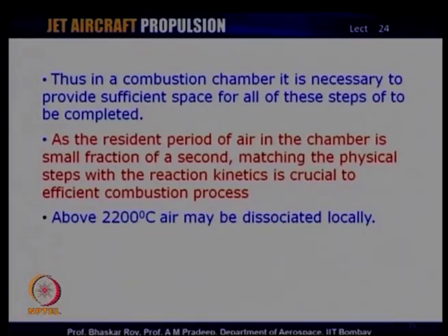Since the residence period inside the combustion chamber is indeed very small, it is necessary that the physical steps and the kinetics of the reaction are matched in time. This is extremely important, because you do have a small fraction of a second, quite often a very small fraction of a second, and within that fraction of a second you need to have a physical matching between the reaction kinetics and the physics of the flow, and this is important.